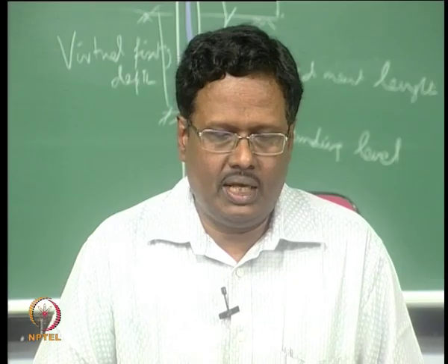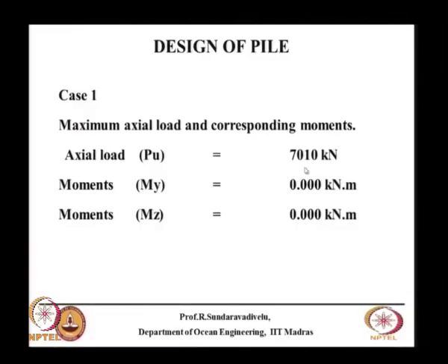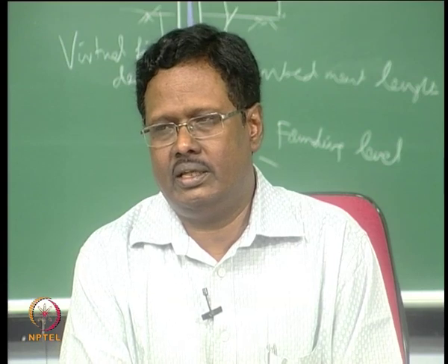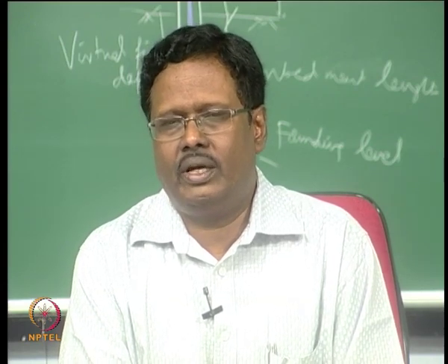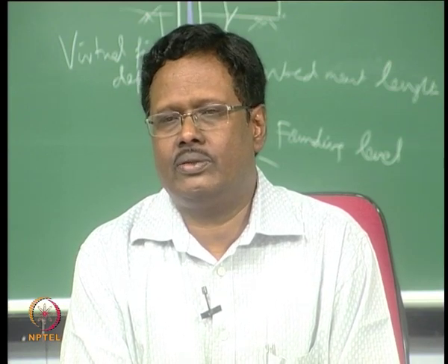So when you talk about the axial load for this particular case, the bending moments are nearly 0, and we have an axial load of about 700 tons. It is a very huge load. So whenever we get this type of load, we have to talk about two types of design. One is the structural design, another is the foundation design. Foundation design always has a certain risk factor associated with it.